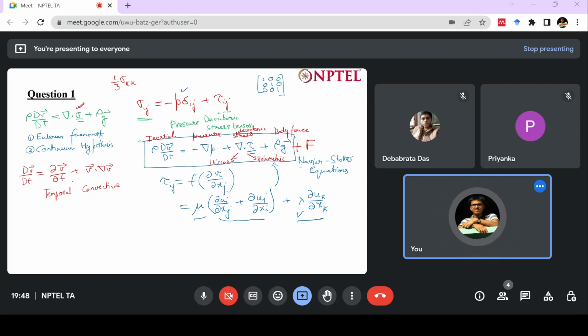We always have to keep in mind we are working in an Eulerian framework. So when we are looking at a point, there will be fluid particles which are coming in and leaving the system. So the temporal derivative focuses on the velocity variations with time at a specific point in space. This is not my acceleration. Acceleration is the whole thing, but del v/del t here is my change in velocity at a particular point in space.